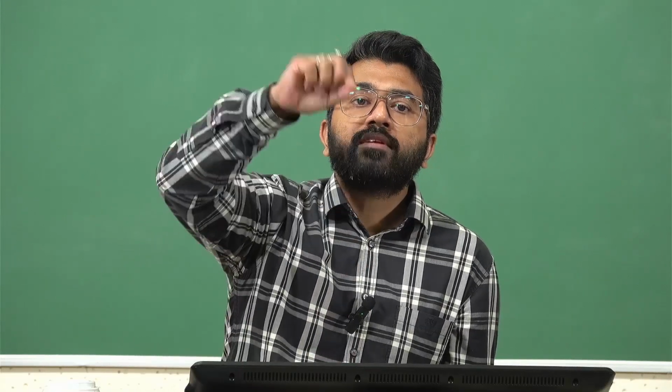So let's say I have a rectangular specimen of length 5 centimeters, width of 1 centimeter and a thickness of 3 millimeters, right? So what is the area of cross section? It is 1 centimeter times 3 millimeters, right? That's the area of cross section, that's my initial area. If I divide the force at any point by this initial area, so I'm just normalizing all the force points by the area, I'll get this stress value. So stress keeps on changing as we keep on pulling the specimen, right?